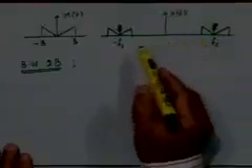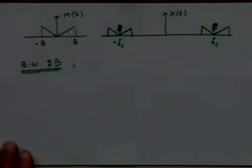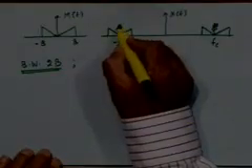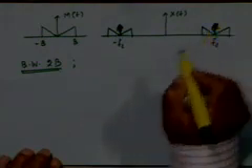There is no carrier component in the suppressed carrier waveform. There is a value of the spectrum at that frequency, surely. It could be 0, it could be something finite depending on the spectrum of the message waveform. But that has to do with the message waveform. It doesn't have to do with the carrier itself. The process of modulation is simply shifting the spectrum from one location to another. That's all we are doing. We are not introducing what we are now calling the carrier component. Is it clear?